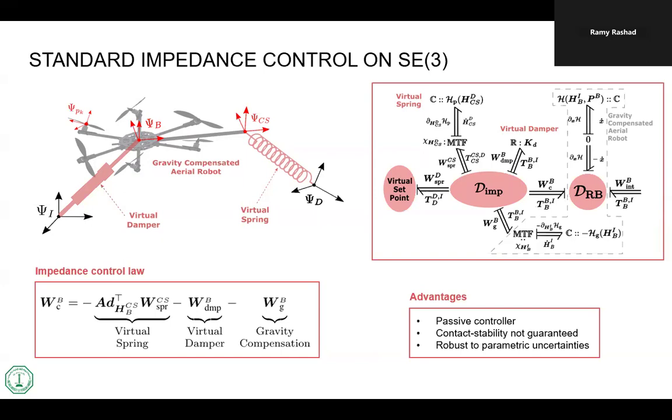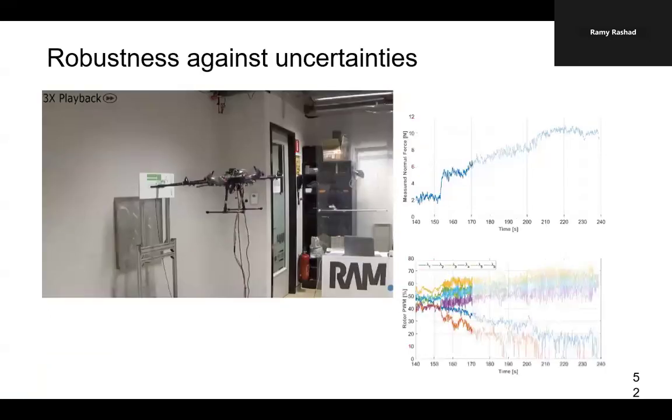So the gravity, you remember the original system had some positive gravitational potential energy. So the Port-Hamiltonian system of the controller would have negative gravitational potential energy. And in the end, you just cancel these two out when you're doing analysis. So this is this C element. This C element is for the spring, and this R element is for the damper. Of course, we have now a different Dirac structure that corresponds to how these ports are connected to each other. Okay, so a little bit more details, but you're going to be seeing the exact same behavior.